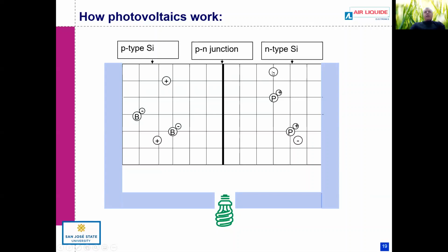And so the electrons that are there in the n-type, if it's substitutionally n-doped silicon, it will have these electrons. The electrons will be in essentially a big anti-bonding orbital, the collective anti-bonding orbital of the silicon.